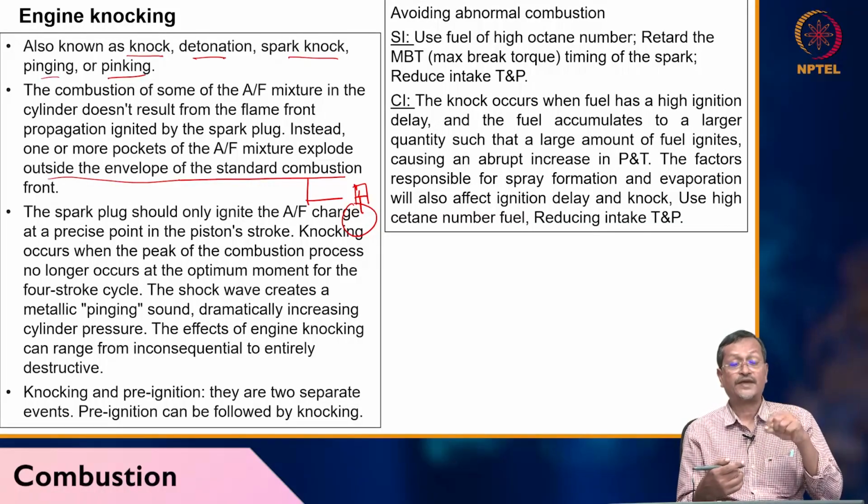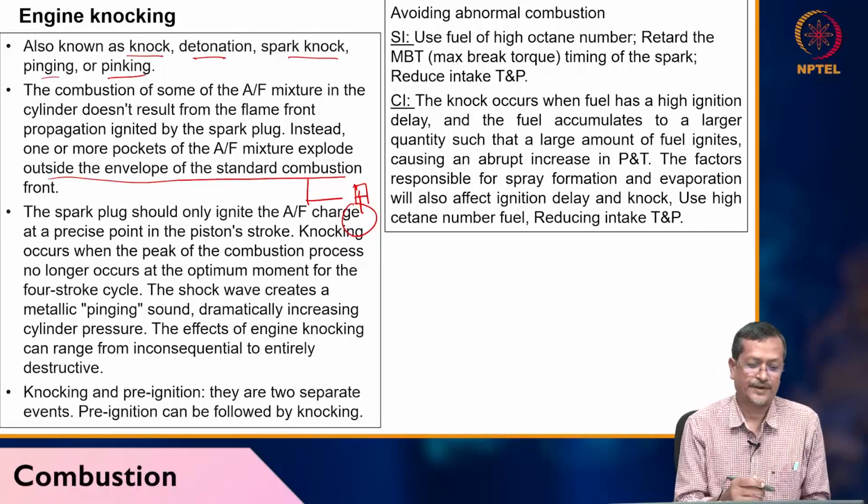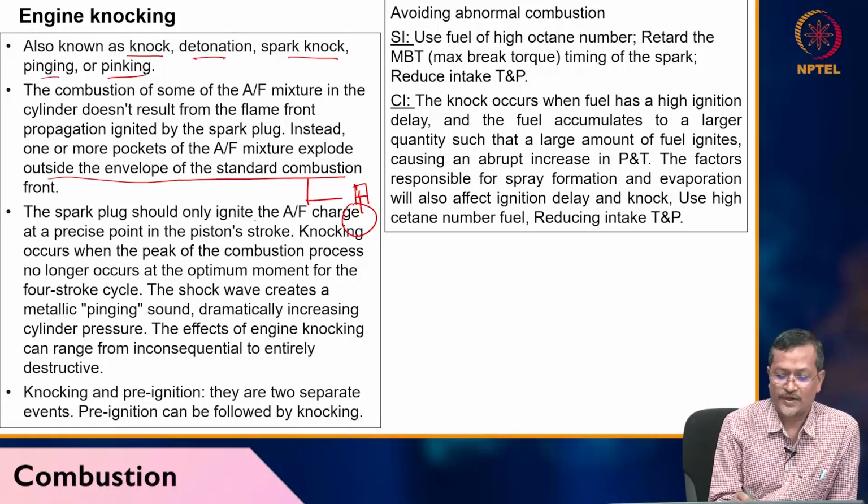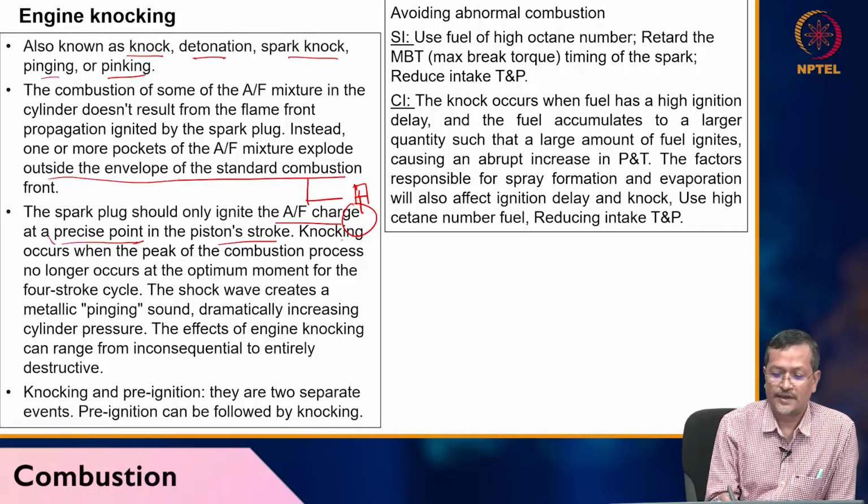So then knocking will be created, engine knocking. The spark plug should only ignite the air-fuel charge at a precise point, not before or after in the piston stroke. Knocking occurs when the peak of the combustion process no longer occurs at the optimum moment of the four-stroke cycle.